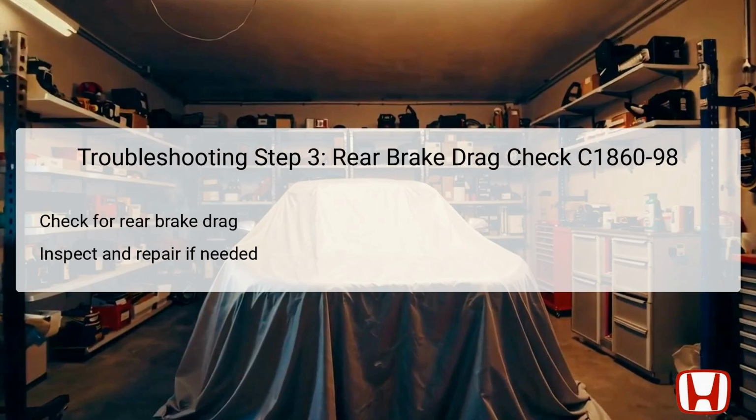In this step, the technician examines the rear brakes for any signs of drag. Brake drag occurs when the brake calipers do not fully release, causing unintended friction and heat buildup, which can impact differential performance.